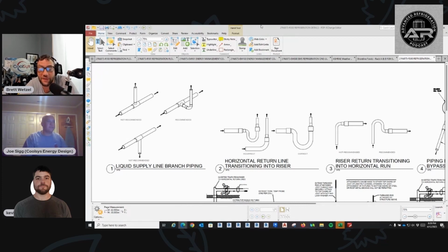Well, that being said, you remember the situation where you had two 8-foot cases together, and then a 2-door end cap with poor flow? Could you essentially bush down at one point, because like you said, the pressure drop in CO2 isn't dramatically bad for the temperature change? In that instance, couldn't you put a bush down to the other two cases to get a little bit more even velocity through? You could, but you run the risk of not serving those other two fixtures properly. All right, never mind. Again, robbing Peter to pay Paul.